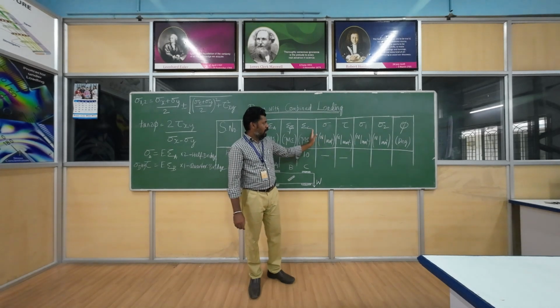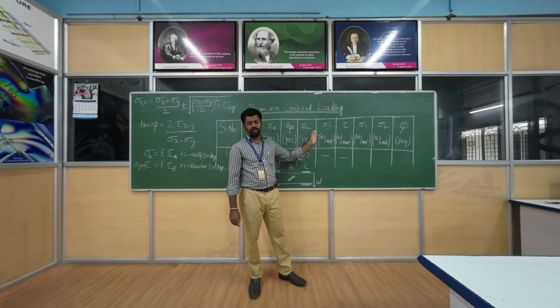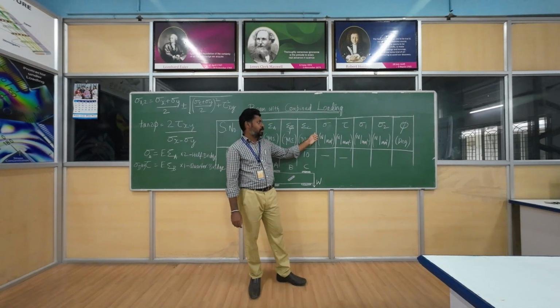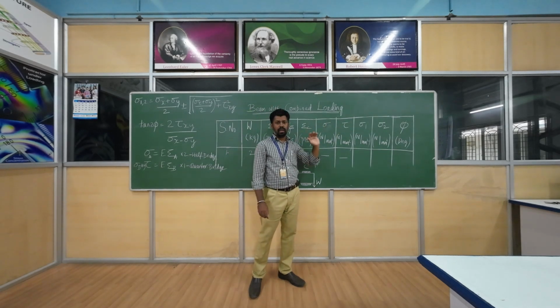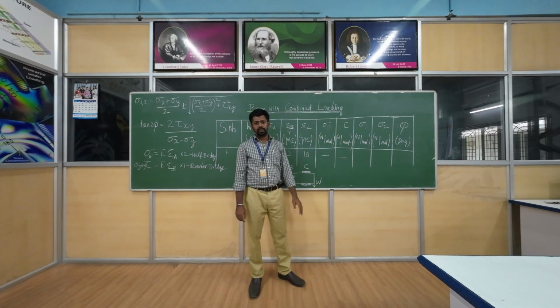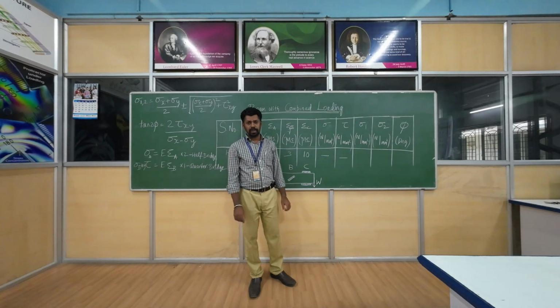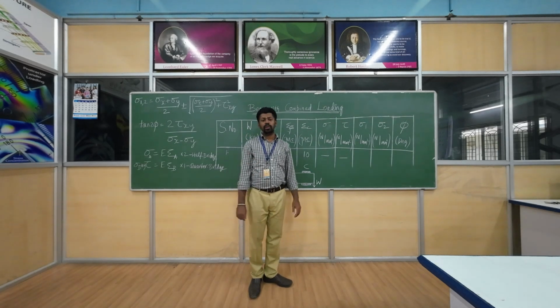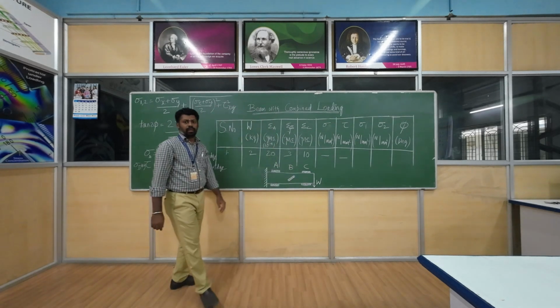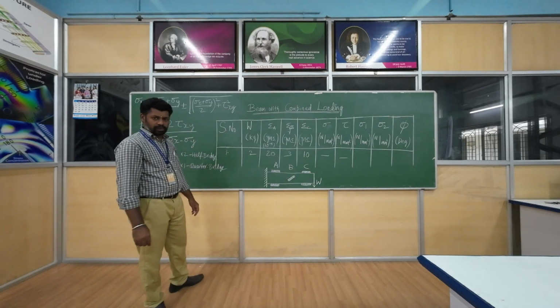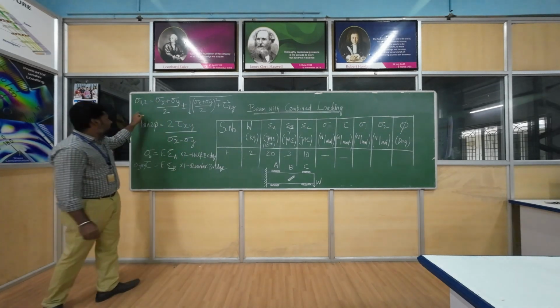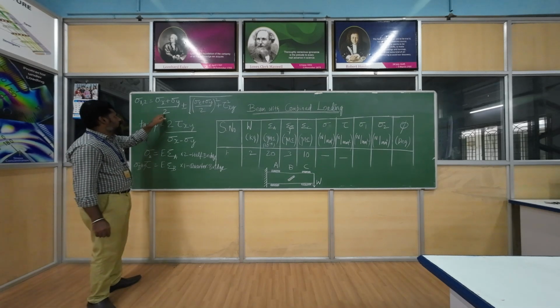Now I have the Cartesian components of the stress, that is, the normal stress and the shear stress. From these Cartesian components, how are we going to compute the principal stress? Again we need to go back to the solid mechanics theory, which we have already seen in that theory course.